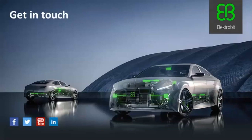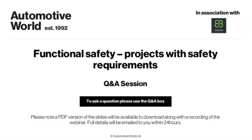Okay, and so how do you protect functionality then, particularly in the ASIL-B ready package? So basically, in the ASIL-B ready package, the basic software does not guarantee the functionality. It actually does focus on the non-interference. So there is no guarantee that there is no other corruption of data within the basic software.